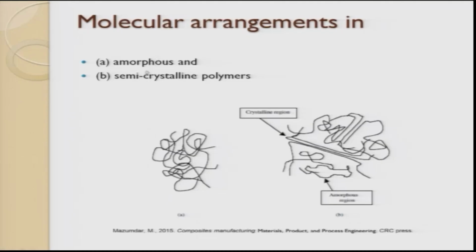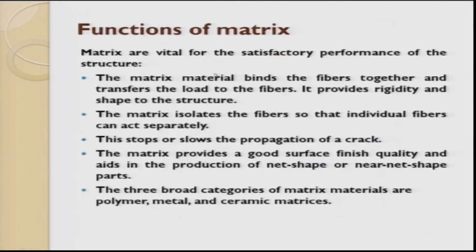And there is another classification called semi-crystalline polymer, where there is some zone in which a fixed arrangement pattern is seen, and in some places there is randomness. Is there a fully crystalline polymer? No, 100% crystalline polymers are not available, or cannot be made. The polymers can be of two classifications: amorphous or semi-crystalline. Depending upon this, properties like transparency and translucency change.